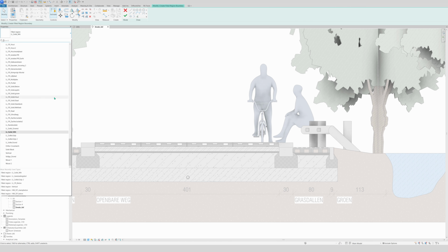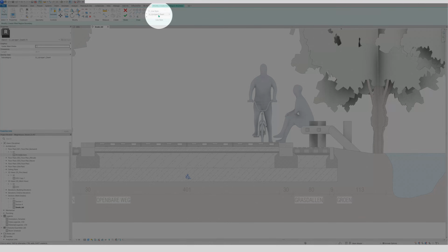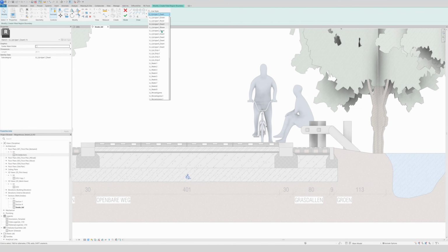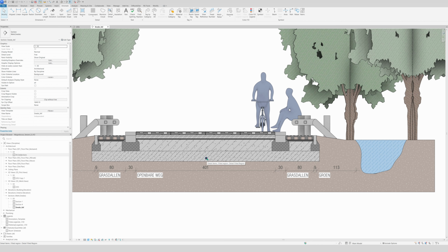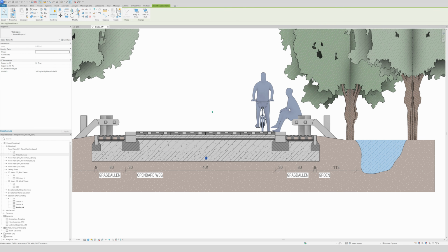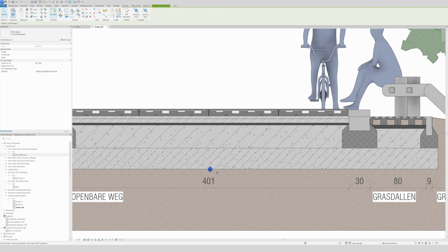Then I'm gonna select the filled region that I want, of course, and I will select lines and go right here to line styles, because I want invisible lines right here. And visible lines, there we go. Then you click on finish editing mode, and there you have our first dot to specify what we are naming, the material. So we're gonna move it a bit with shortcut MV, and then with the arrow keys I can place it more like this, and then I'm gonna copy it for the different materials.